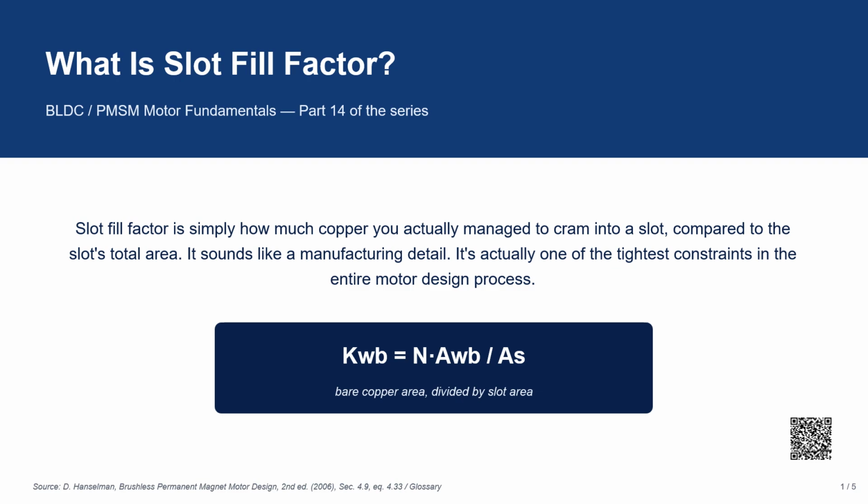Slot fill factor. On the surface, this sounds like a manufacturing detail. How much copper you actually manage to cram into a slot, compared to the slot's total cross-sectional area. But this one ratio turns out to be one of the tightest, most fundamental constraints in the entire motor design